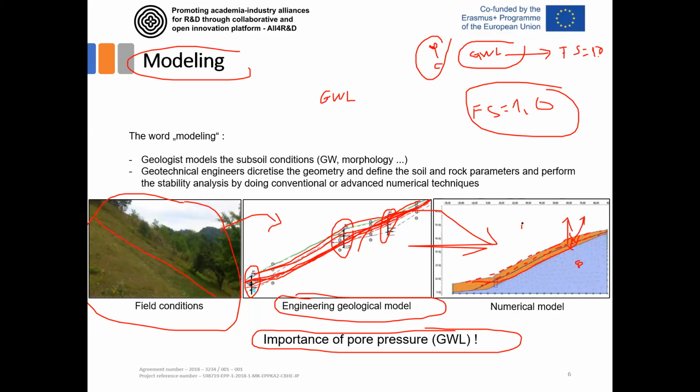Then the safety factor will go from 1 to a very high value, very much above 1. But what if at the moment of failure the groundwater was here? Then this drainage will reduce the groundwater level by only 1 meter. The less we reduce the groundwater, the less we influence the safety factor, and the smaller the increment of the safety factor from 1 to something above 1.